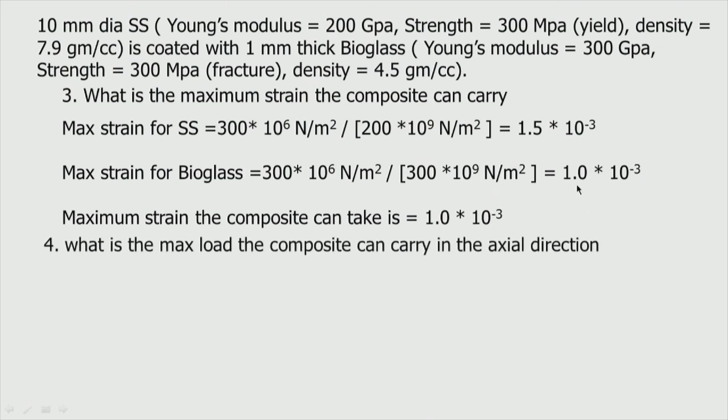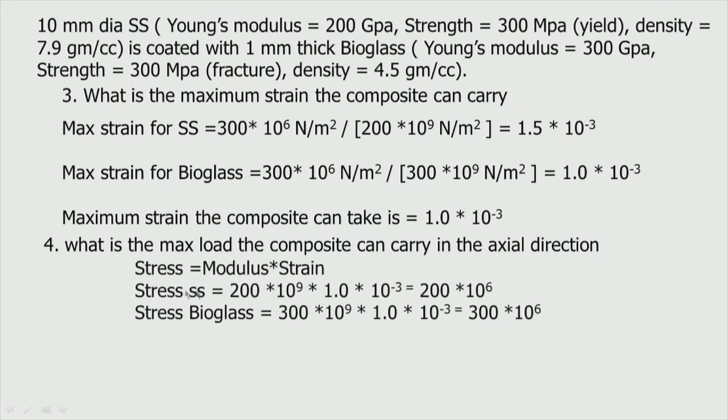Next part, what is the maximum load the composite can carry in the axial direction? We will assume this as our strain. Load, as you know, force by area, is equal to stress. So, stress is the modulus into strain.